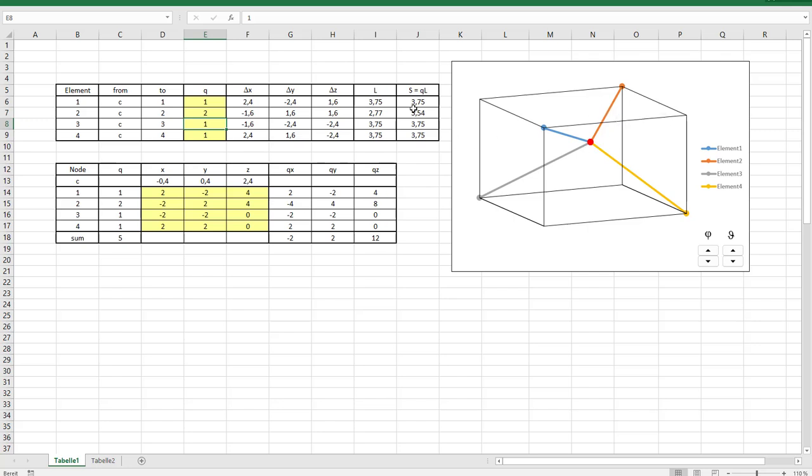If we just refer to the forces in the geometry of equilibrium, these are the results after form finding, and it's hard to understand or see the relation to the force densities. That's one of the dangerous parts of the force density method, that people may mix up the force density with the pre-stress forces. That gives a trend that a small force density refers to a small pre-stress force and a large one to a large one, but it's impossible to really guess what the final forces are if you just look at the force densities.